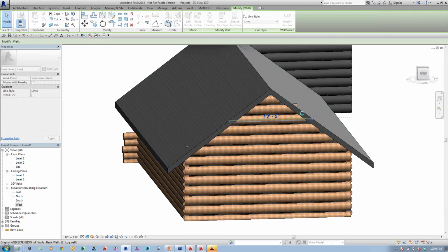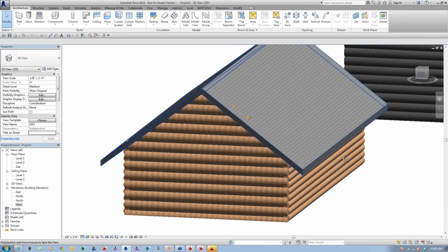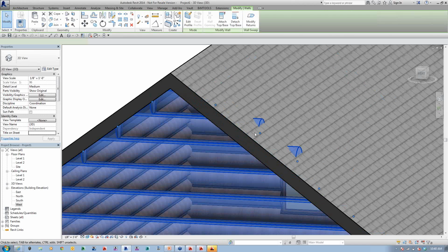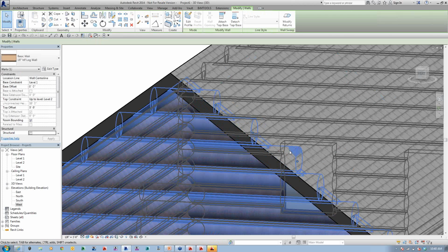So as I'm designing it, I might have a couple of these peaks in here, and I have to go in and hide those. So there's a couple ways I can do it. I can select these walls again and push that inside. One of the tricks I used to do early on was that I would build the roof a lot thicker than I needed it. Now, once we started going to SIPS roofs and doing things like that, it made it a lot easier. I just buried it inside. It was a lot more to do, a lot more interesting and fun to do.